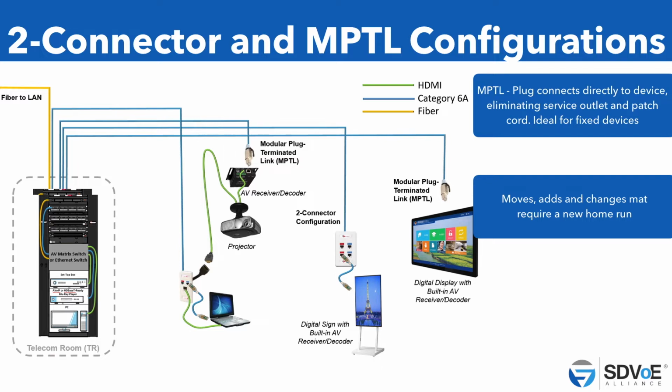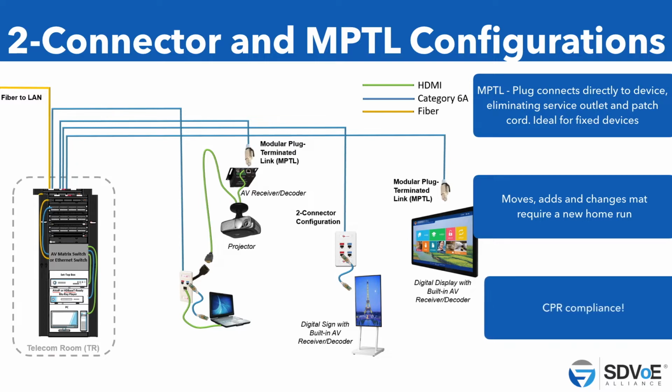So every cable now that's manufactured that goes into a building in Europe needs to meet a specific class. Typically these classes will be either a Class B cable, or Class C cable, or a Class D. Nothing to do with performance in terms of data throughput. It is a legal requirement that the cables being installed into buildings do meet the fire classes. If anybody wants to talk to me about that after, more than happy to speak about it.